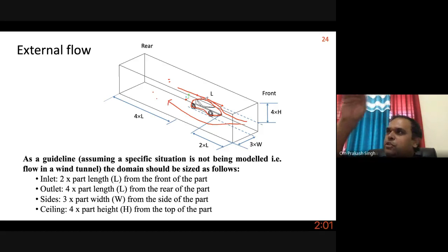So when you remove it, its replica is created, and only the surface remains there, and inside it will be hollow, there will be nothing inside. So the CFD will fill up the mesh only outside, not inside. You can do the volume meshing only that way. In this case there are two volumes. So one volume has to be hollow if there is one zone, and it has to be closed.